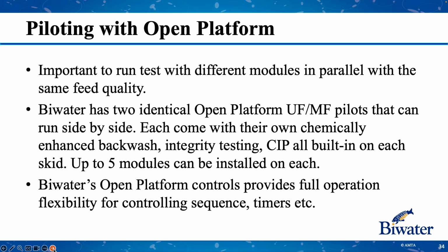So we try to keep it as compact as possible. That means selecting, installing, and fabricating with equipment that's going to cover the majority of the most likely modules we're going to use. We can't put in infinitely sized pumps and infinitely switchable actuated valves.